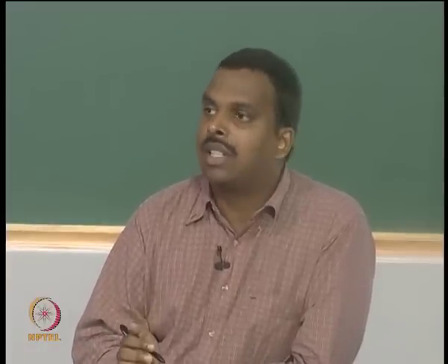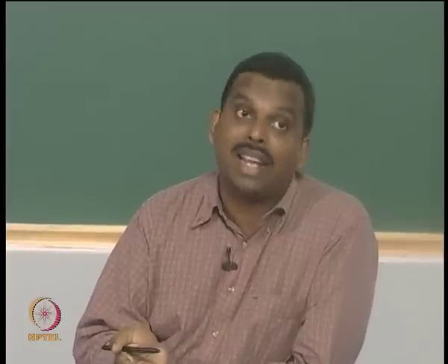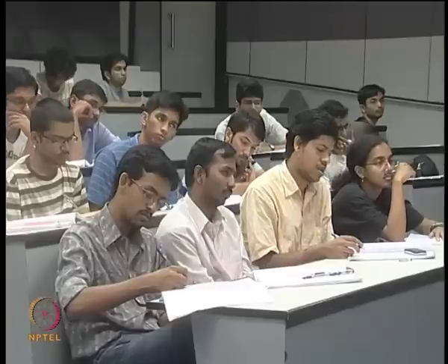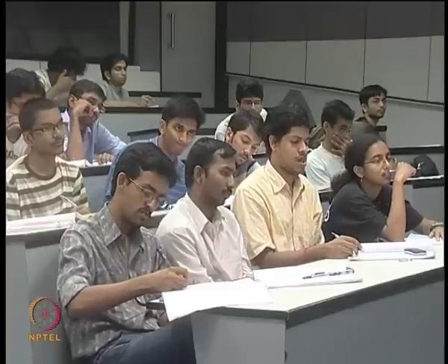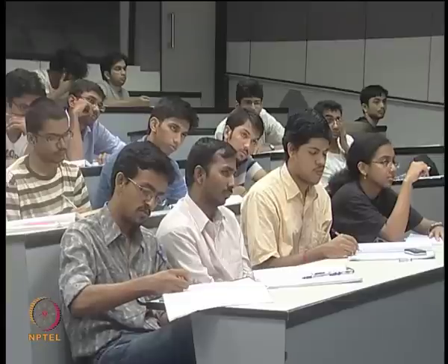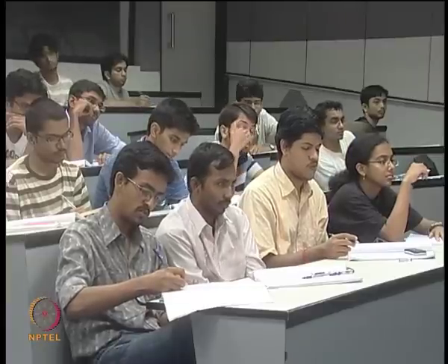On the other hand, if you decide my complexity is too high, I can't do all of that, one choice is the hard decision decoder. Then you are back in the same old picture as before, the syndrome decoding world, where you simply come back to bits and you are happy. Okay. So, what we will see next is what to do if you do not want to do hard decision decoding.